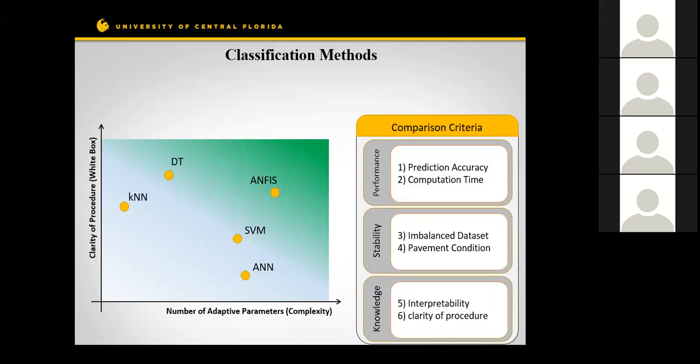And that's a well-known problem in data science, because we know imbalanced data sets can hurt the accuracy and performance of the classifiers. That is something that we had in mind. And the other thing is that when we train one classifier to detect cracks, we are very concerned that if we apply it to clear pavements, it might overestimate cracks, and if we apply it to very damaged or poor condition pavements, it might underestimate.